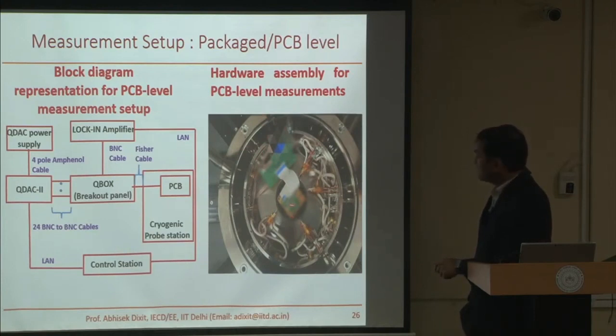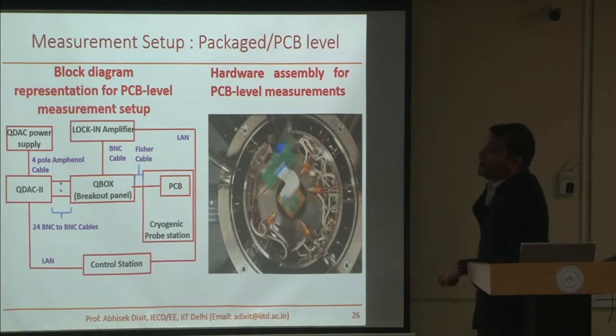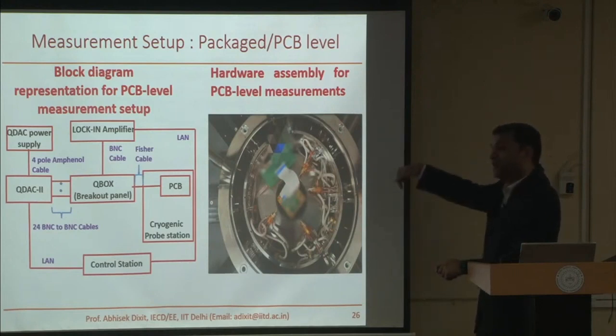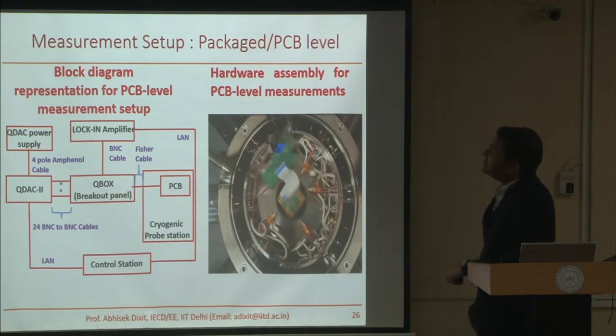Of course, you have to have thermal bobbins and all kinds of cryo technology to even cool down the electrical signal. The electrons which are coming from here are coming at a higher temperature, right? If you don't cool the electrons, all your measurements are destroyed. So you have thermal anchors which are tied to this stage somewhere. Electrons first go there, get cooled off, and then go into your device, so that they don't heat it up. So fascinating work, a lot of new characterization challenges.